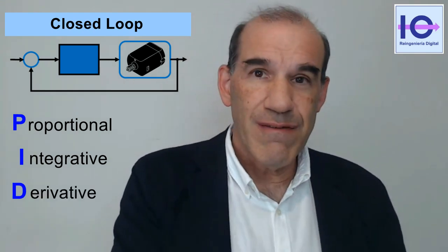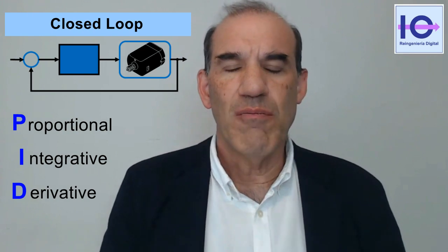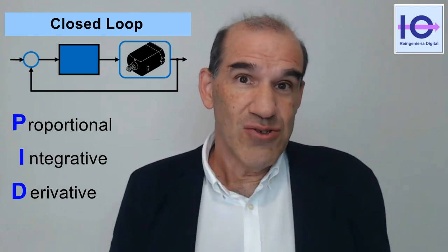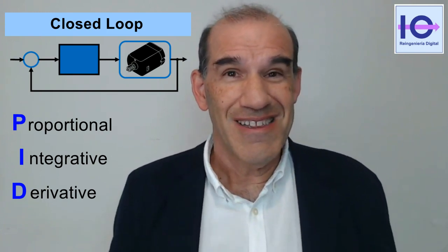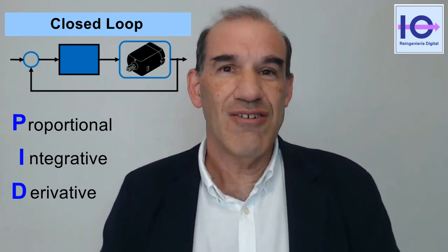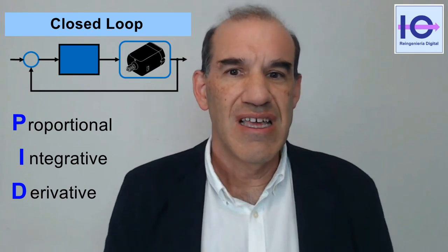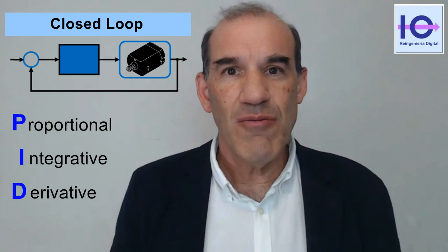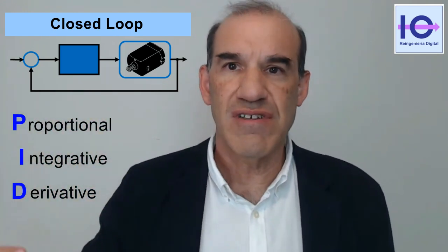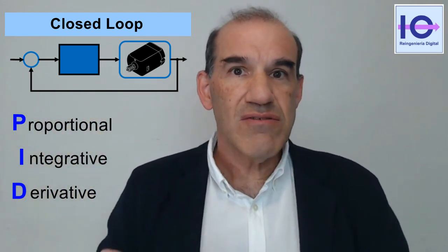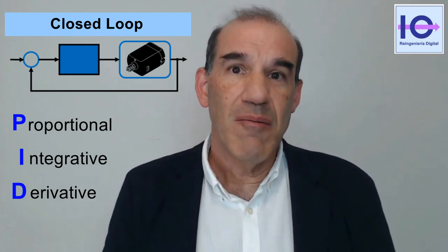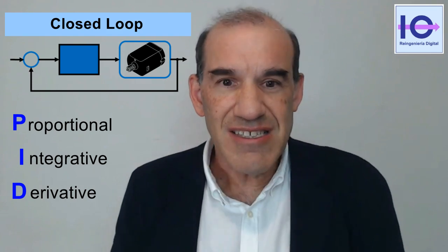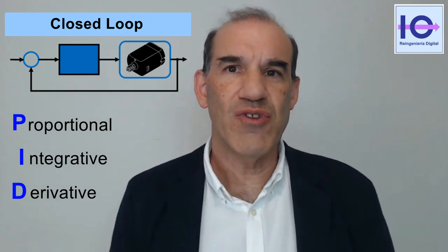And so we need the third component, the D component or derivative component. The derivative component uses derivatives that, as you may remember, are a kind of measure of change. So to a certain extent, the derivative component anticipates the future, and so allows us to avoid overreaction, but on the contrary, makes the system more sensitive to noise.